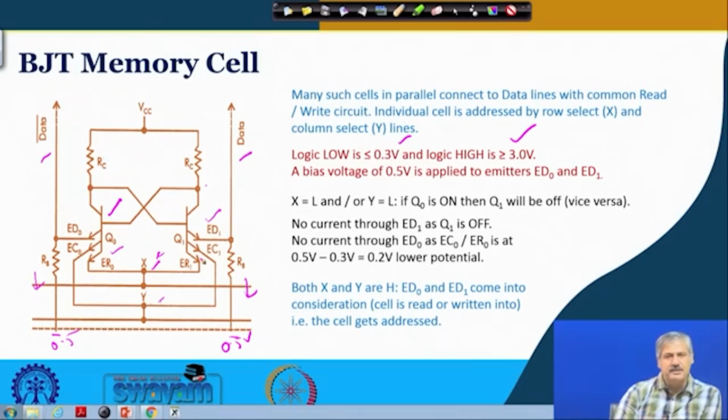This part is the major thing, and this is similar for your MOS based cell or CMOS based cell also, where two inverters will be connected back to back in a cross coupled manner, rather like this, where we can see the feedback coming in this manner. Similar things will be there for the other cases, which will offer a bistable mode of operation for this particular block.